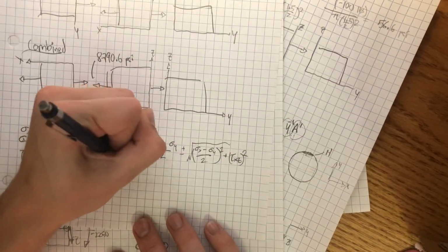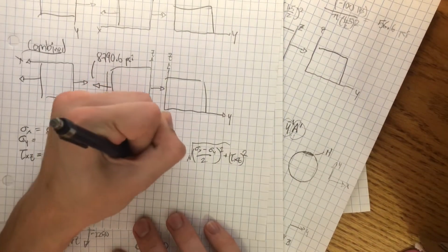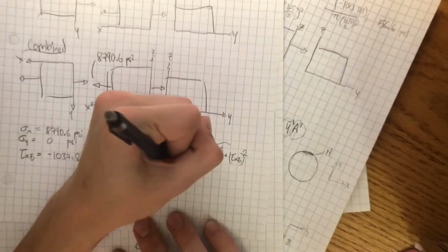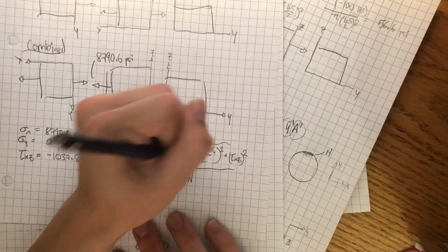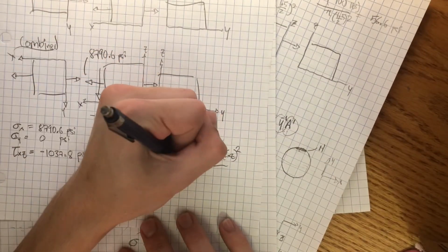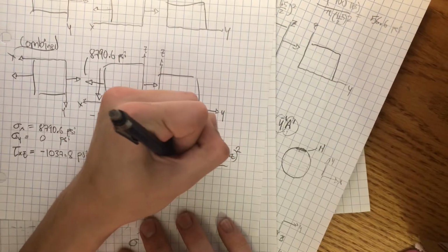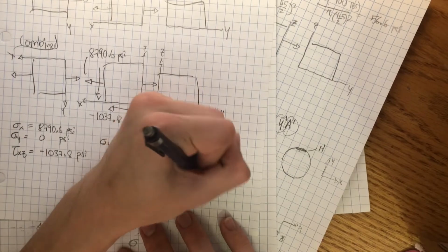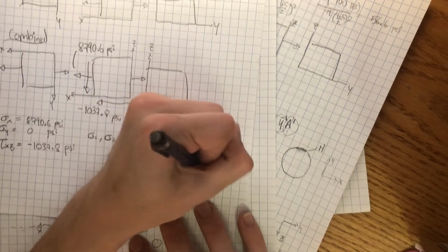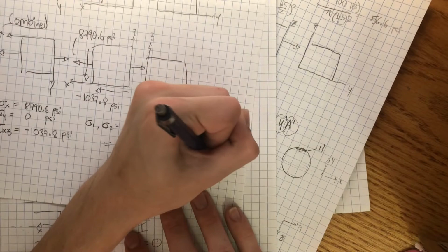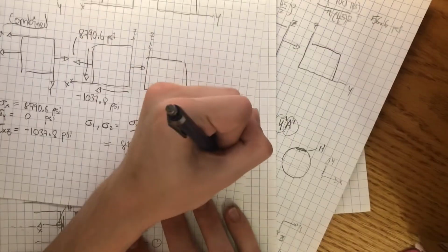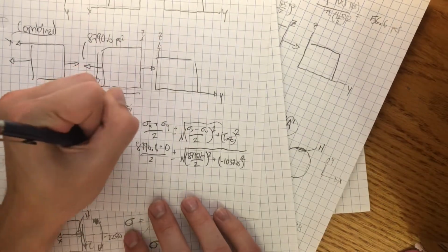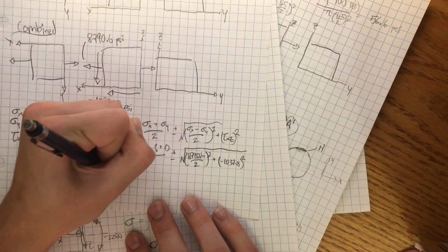So if we plug everything in, we end up with 8790.6 plus 0 over 2 plus or minus the square root of 8790.6 over 2 squared plus negative 1037.8 squared, like that. So then you end up with sigma 1 and sigma 2 values